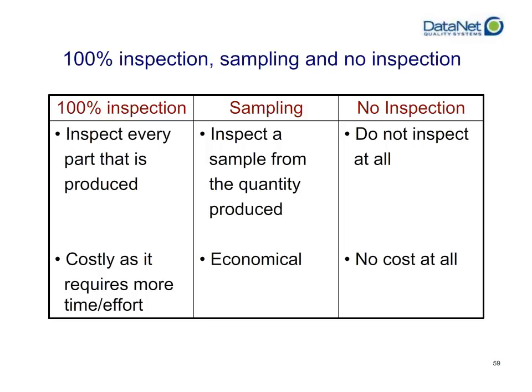Very important to realize there's different ways you could handle it, but sampling for SPC purposes is the way to go and the way to gain the most value. Now, there's the question about, well, if I'm sampling, how can I know if everything that I produce that I have not actually sampled, if I'm not doing 100% inspection, is still under control or in tolerance? We're using statistics, and we're going to talk later about the bell curve and whether or not we're actually able to produce things repeatably.